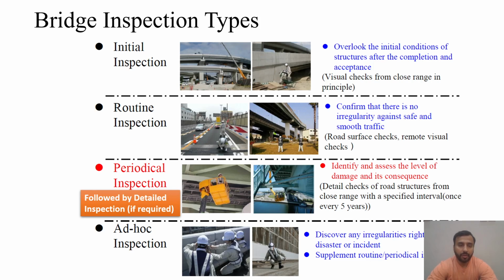After periodic inspection, normally it's a scrutiny process in which a general but more detailed inspection as compared to routine inspection is done. The general condition is recorded and different prioritization formulas are used so that critical structures which require imminent or the earliest possible repair can be identified. So the detailed inspection of such identified bridges is carried out by the expert bridge engineers who then carry out the repair designs for the repair of the bridges.